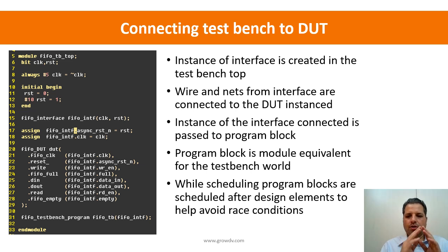So just to recap from the previous slide, anytime a DUT needs to be connected to the test bench in SystemVerilog, it is done through interface constructs. So that's the first point to remember. Second point, there exists a concept of modport, and modport provides the views to the interface to help you set the directions. Then there exists a clocking block that helps you provide information about when a signal needs to be driven and when it needs to be sampled. I think these 3 points are fairly simple. Just hold them in the back of your mind.